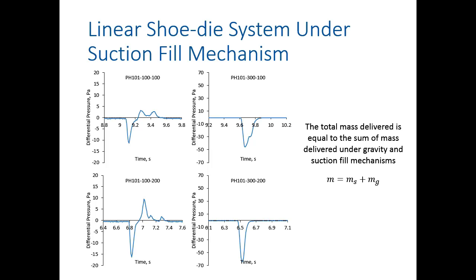Based on the differential pressure measurements, we had the same observations. Initially in the experiments we have a sudden drop in the differential pressure inside the die, followed by an increase in the differential pressure as the suction field period is completed. For really large shoe velocities, because the gravity time is really small, we don't see a large increase in terms of the differential pressure inside the die.